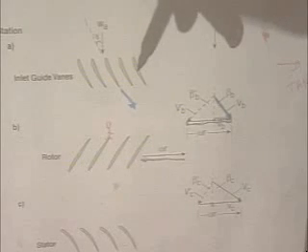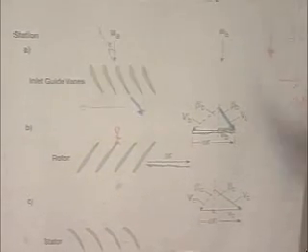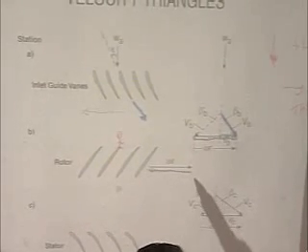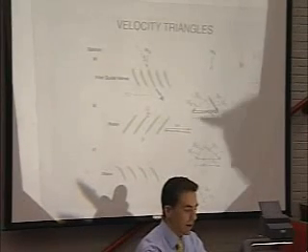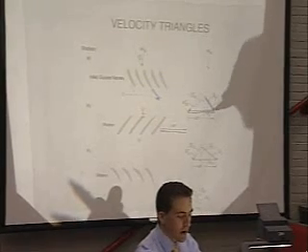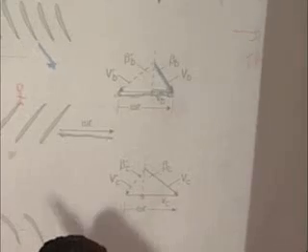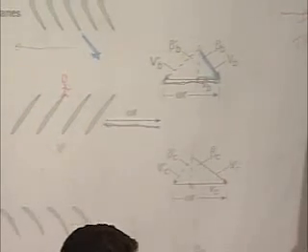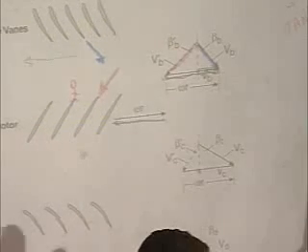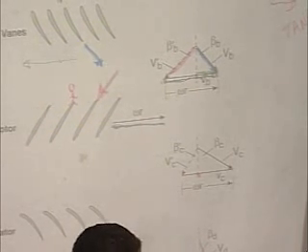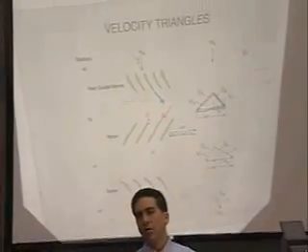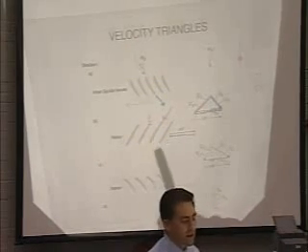So this reference frame is moving past this one in this direction at omega r, or from this perspective, this one's moving past this one in this direction. That was a lot of thises in that statement. Let me finish the vector addition here, and then we'll talk about it. If I add the stationary frame flow vector to the omega r, that gets me to the rotating frame. I then end up with the relative frame velocity, which you can see lines up nicely with these blades. So we've just done a frame change. Now, it makes sense because it lines up with the blades, and I told you it ought to roughly line up with the blades. Does it make sense to you conceptually?